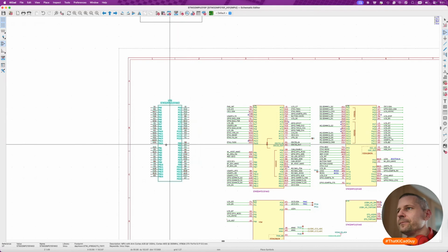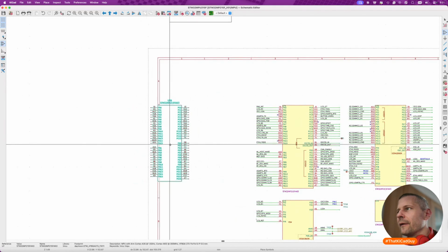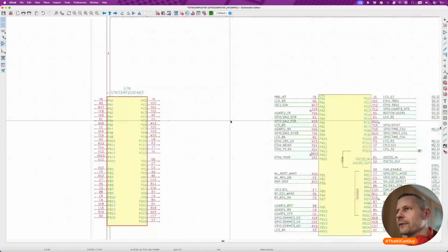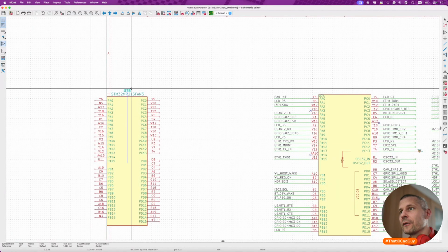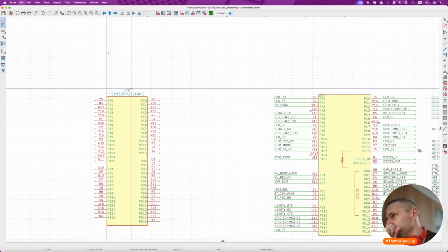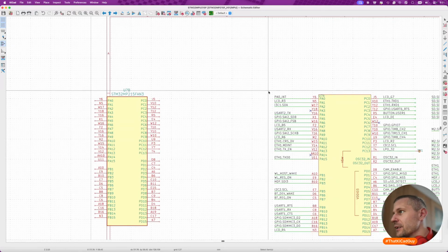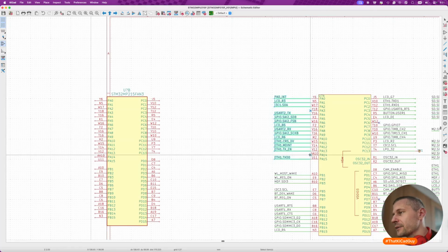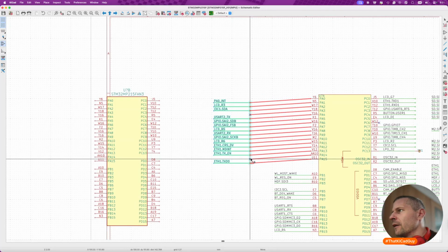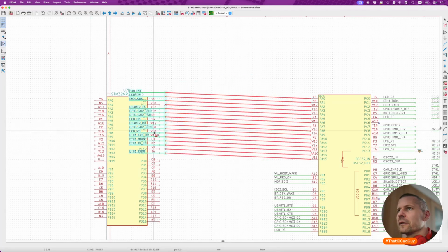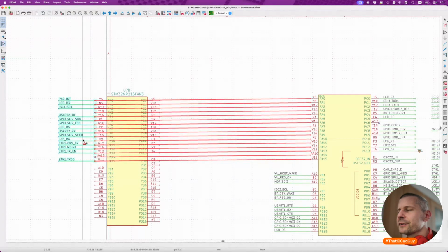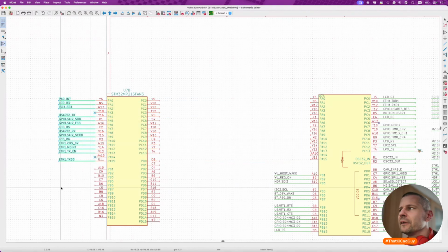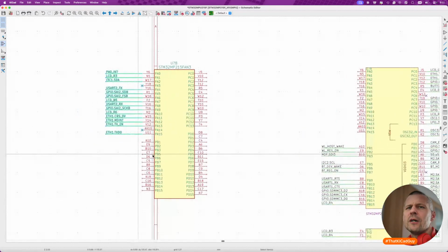And yeah, I'll start here and copy port by port because it ensures the consistency of the 16 nets are identical. Yeah, this new feature of KiCad is interesting, but I don't know how to disable it.